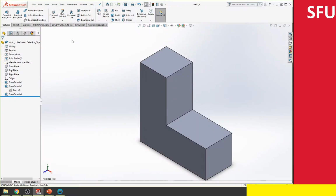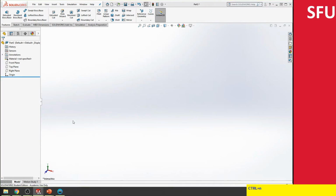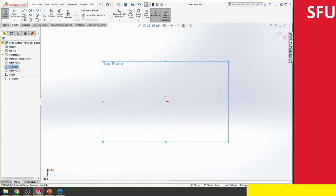So let's do a new part. We are going to create this on the top plane, which is also the XZ plane here. I'm going to create a new sketch. If I wanted, I can center my table about this point. For that, I would create the center rectangle.